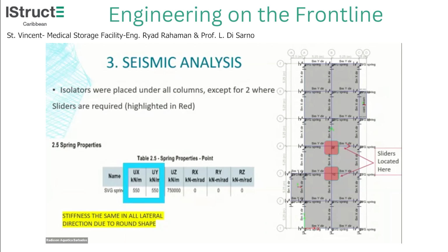Different, no lateral resistance. The rubber isolators have the lateral resistance. However, you had to keep playing around with the locations of both of them and interchanging. Why? Because you want to make sure your center of mass and center of rigidity are not off, so you don't get that twisting, that torsion, etc.